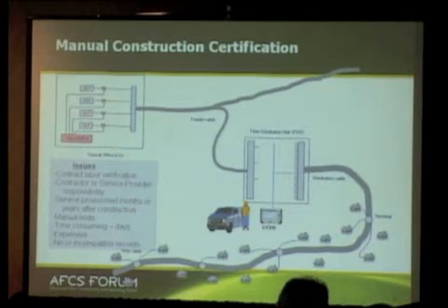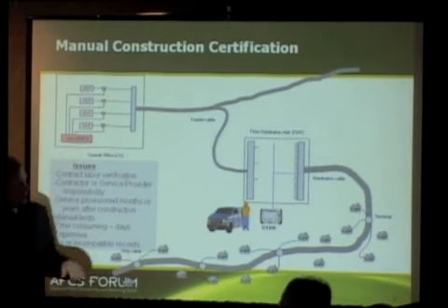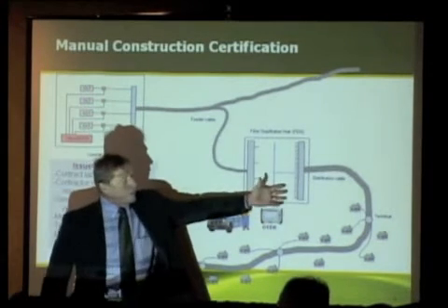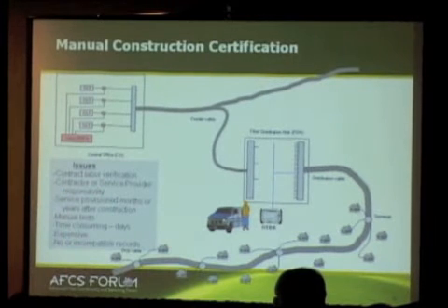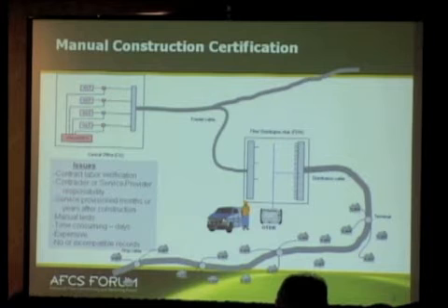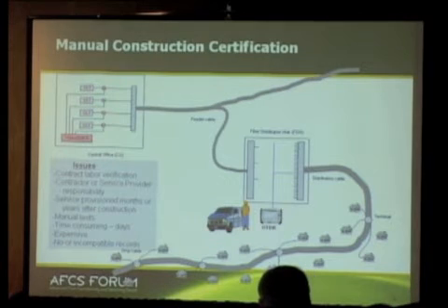Maybe I can better explain it here. You can have the splitter network here and here. This is principally a European type model where they'll have a 2-to-1 or a 4-to-1 splitter in the central office and an 8-to-1 splitter that is passive in the central office or the outside plant. But you still need to then connect these different fiber segments and test them all.